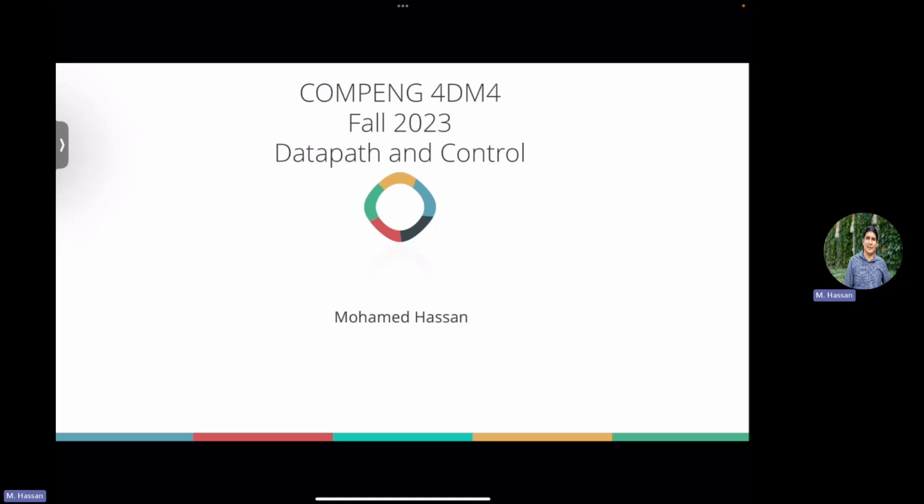If you remember from our lecture 1, the control path is the one that gets the instruction from the memory, which is what we call a fetch operation, decodes it to understand whether this is an add, a multiply, a division, and then feeds the control signals to different functional units, including arithmetic units, register file, memories, etc., to be able to execute the actual operation.